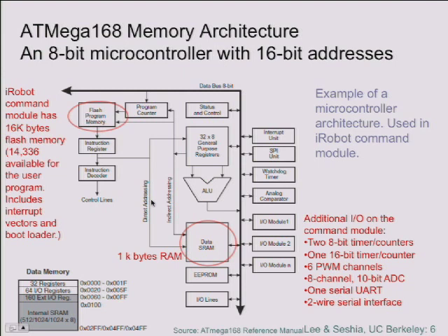It's interesting to try to restructure your thinking to what you can do with very small amounts of memory. The random access memory is 1 kilobyte, versus 4 gigabytes on this thing. That's a big difference. And the way that the data memory is organized is shown down here. There's a logical address space, which is shown using hexadecimal numbers here for the addresses.